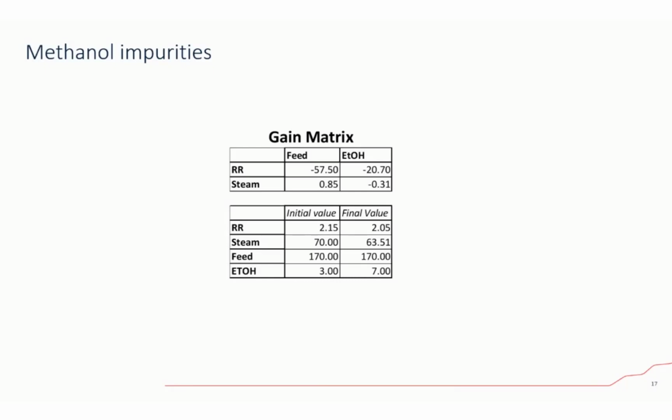We go to the plant and we first make sure that the instrumentation is working fine, at least all the critical instrumentation, that all the critical and relevant PID loops are working properly and properly tuned, that the base layer strategy is properly configured, and also that the control system can accommodate an external tool. Only when we have made sure of all of those things can we say it is APC ready.